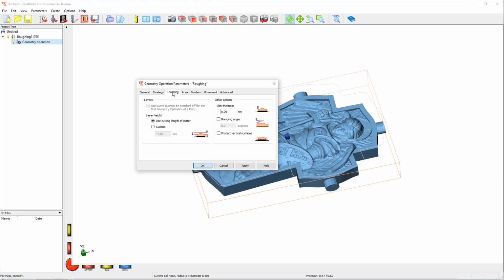Now roughing, in wax, I'd cut this all the way down in one shot because it's very low load on the cutter. If you try to do this in wood or metal, completely different story. And again, that math from the first thing is worked over here. So the depth of cut, DOC, you'll see it referred to a lot, is how far down can the cutter cut into the material before I'm risking breaking the cutter. Now, if you worked in the first menu and you set your speeds a lot slower, you could probably get away with a lot deeper depth of cut.